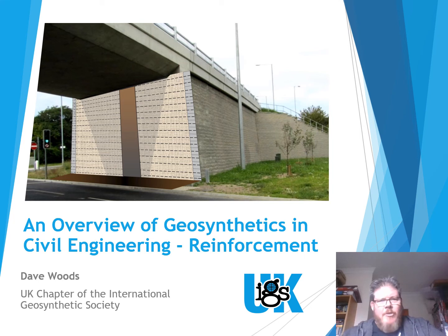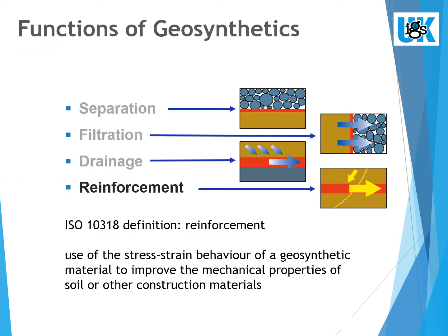Welcome to the chapter on the reinforcement function of geosynthetics. The reinforcement function is defined as the use of the stress-strain behavior of a geosynthetic material to improve the mechanical properties of soil or other construction materials. This definition primarily refers to reinforced soil structures and the base of embankments.